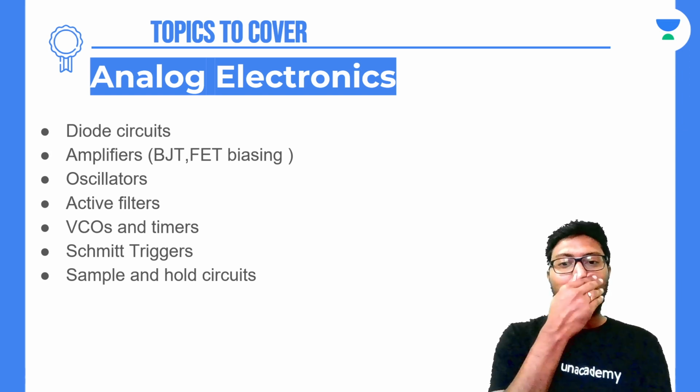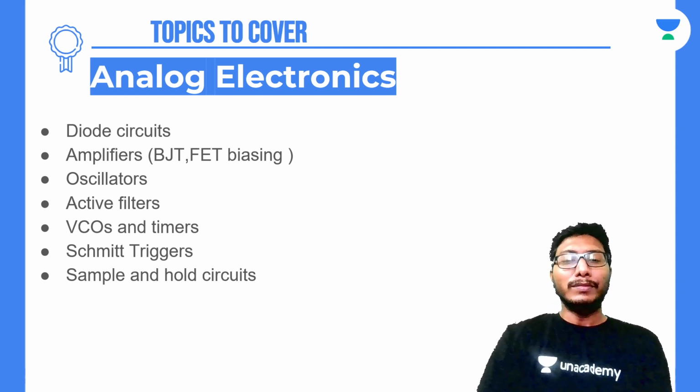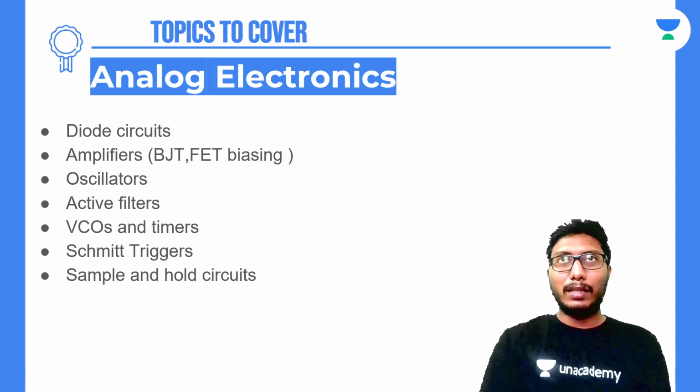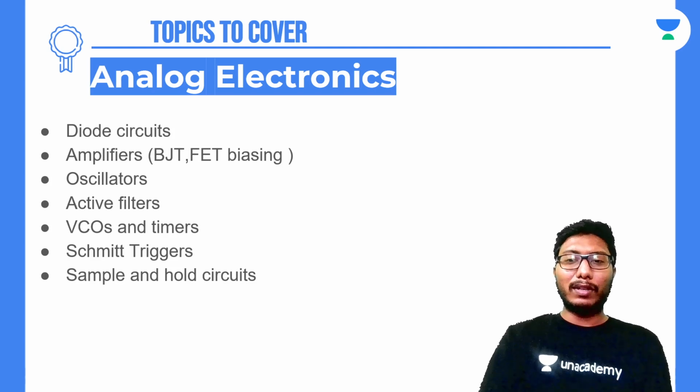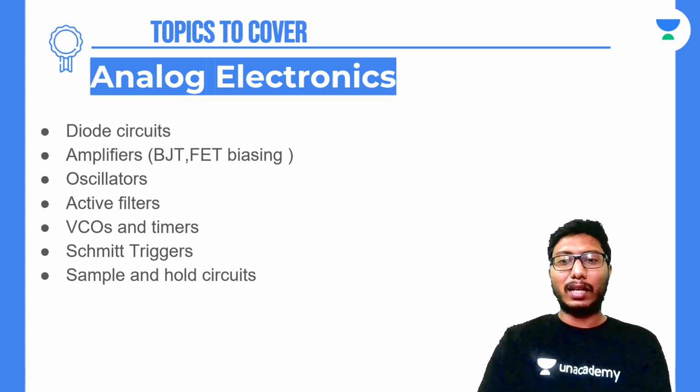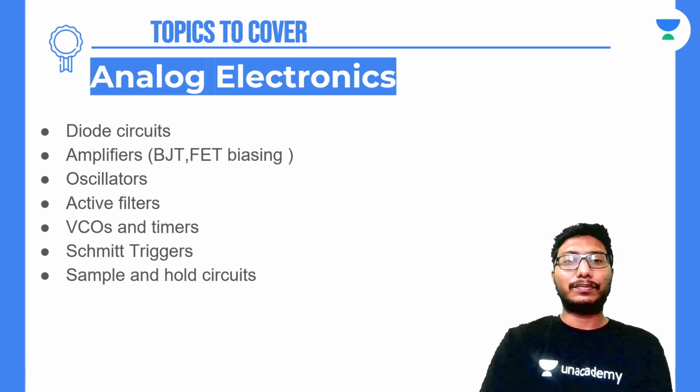Simply you will be given a circuit and you will be asked to find the input or output resistance, or output impedances, or output capacitances, or say inductances. So if this type of question is asked to you in the examination, then you can use Miller's theorem for solving the problem. It will not be explicitly asked. You should know it from the problem definition, what the problem is asking.